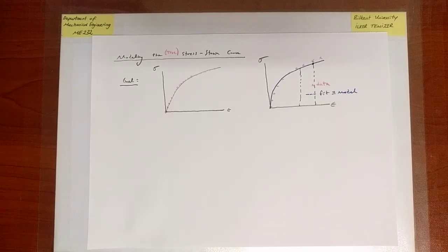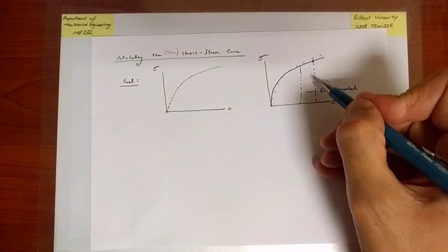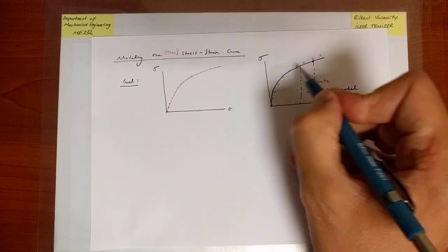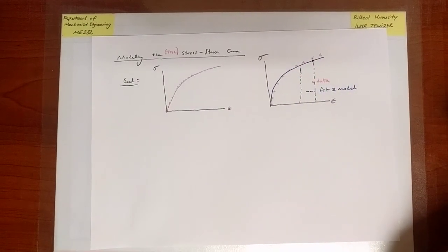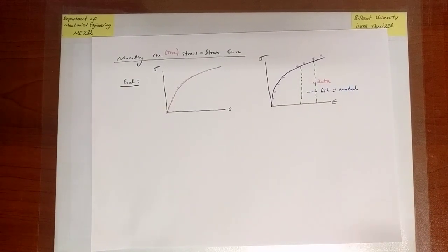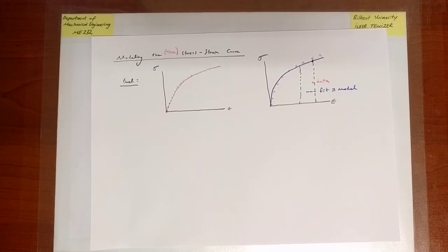That deformation is in the plastic region, so I need a function that can tell me, given a certain amount of deformation in the plastic region, what is the corresponding load that I need to apply, right? And if you know those loads, then you can determine your manufacturing operations and the machines that carry them out properly within certain safety factors, of course.